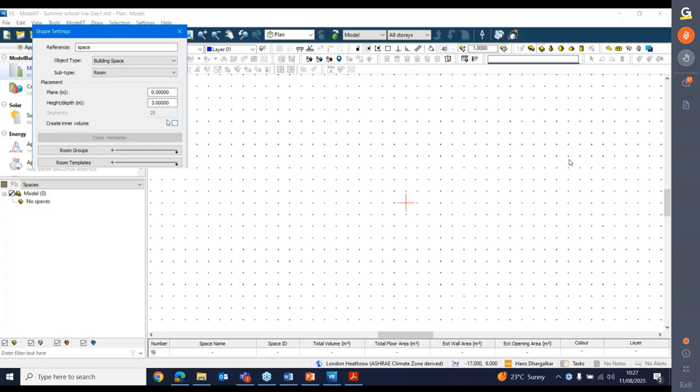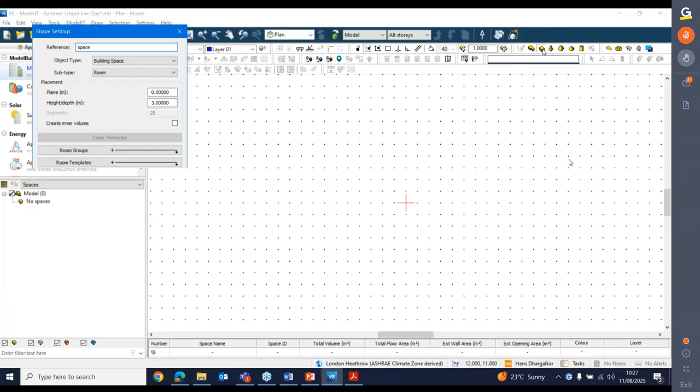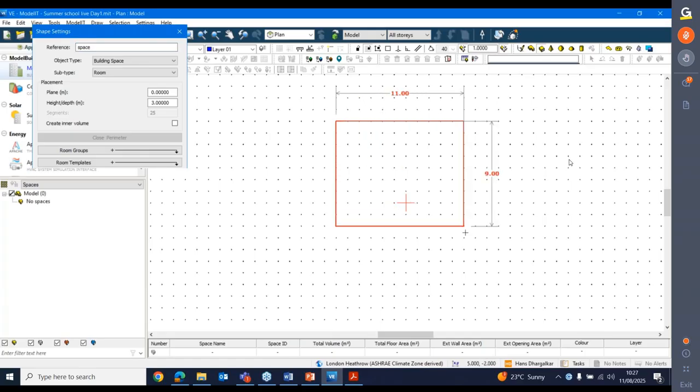So there's my settings there. So all we do, I've got grid lock switched on. I've got my grid size set to 1 meter in each direction. So all we do is we click on the shape we want to draw, which in this case is a prism, and we click for one corner, and you place your mouse to define the opposite corner, and you can see it's locking to the grid, by the way, because I've got grid lock switched on. Okay, and I finish it off with a second click. So there's my first room drawn.